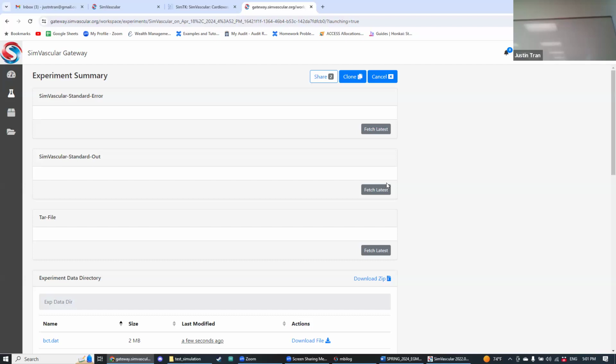I think overall your model actually looks really nice, and I don't think we're going to have too many issues, maybe with RAM. If your mesh size is too small, there may not be enough memory to hold it all. So I would maybe play with the mesh size. You can see it's kind of helping a little bit. I'll probably run the actual simulation on my school one, because I didn't want to use gigs of RAM. Yeah, it's going to be tough. So I would smooth it here and then transport the project to your PC, and then you can run the mesh. Okay, for sure.